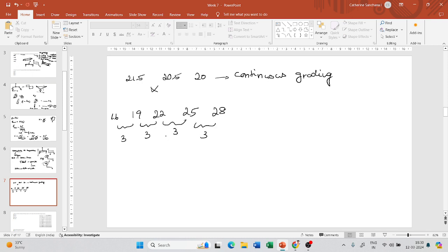If the temperature at which the maximum value of G star into sine delta, 6000 kPa, falls anywhere in between, you should not take that value, but you have to pick either one of these values, because that is the PG grade.